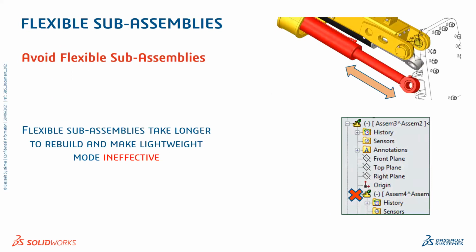The flexible subassemblies will always take much more time. So use flexible subassemblies only wherever necessary. We do not need to use flexible assemblies everywhere, or you can control these features using configurations also. Hence avoid flexible subassemblies, which will impact the rebuild time.